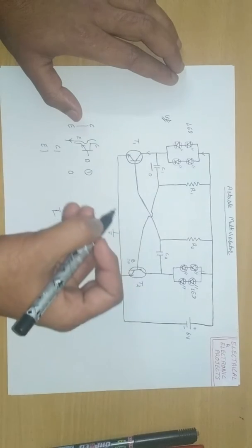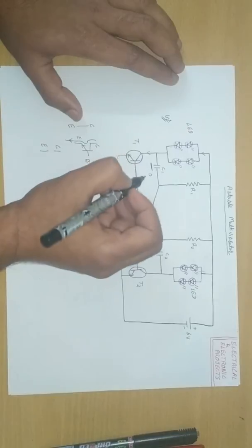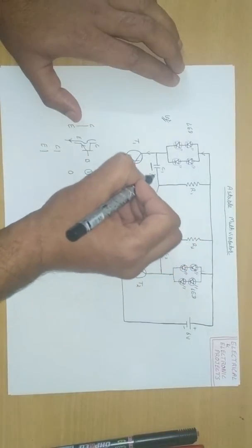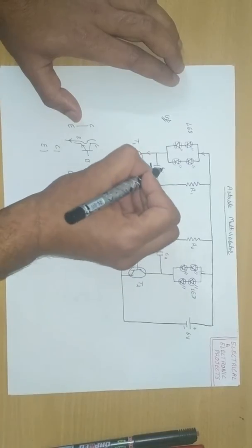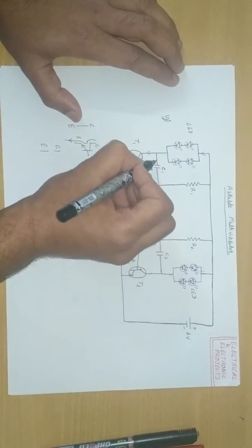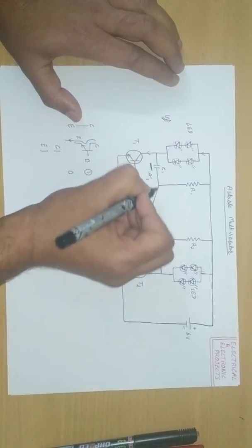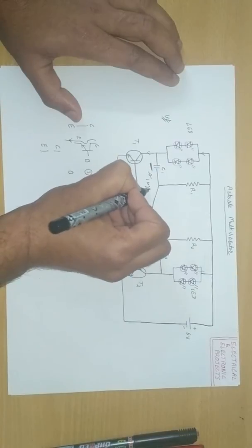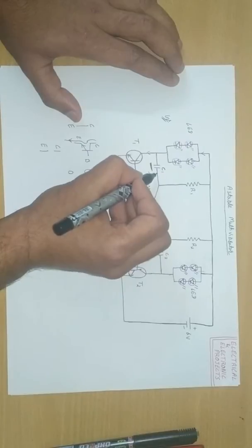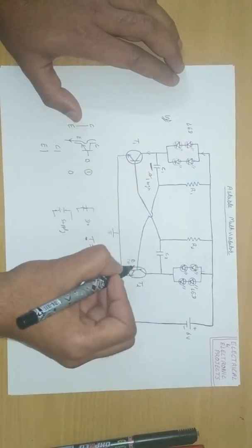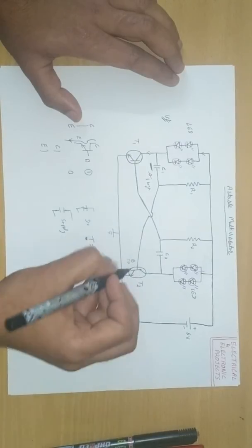After some time constant, when this capacitor C1 is charged, because current flows from here and initially it acts as a short circuit, the voltage across it is maximum, say 1. Instead of 0, now the voltage is 1, or say high. When there is high voltage across it, this high voltage goes to the base terminal of the transistor T2.